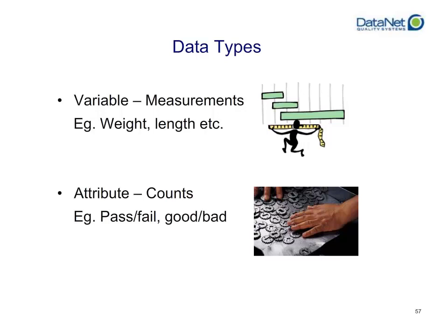Now, if you have data that is statistical in nature but can't necessarily be recorded in the form of a measurement, things like true or false, pass or fail, things that are qualitative in nature, that would go into attribute data and would be recorded with attribute type charts.